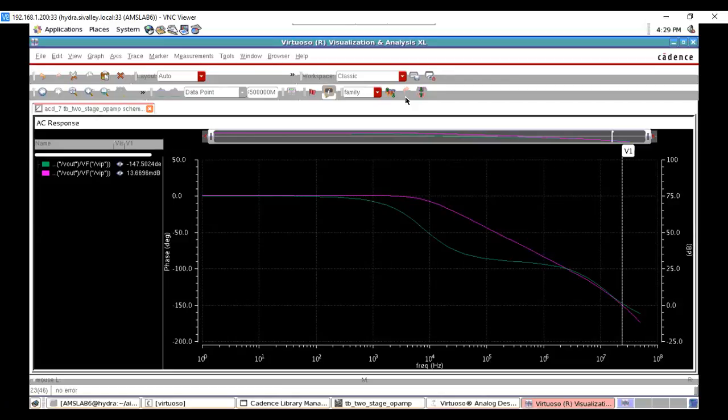Basically I want my Opamp in the time domain to be very fast, operating at high frequency so that my time becomes lesser. High frequency means the unity gain bandwidth should be higher, and at the unity gain bandwidth, your phase margin should be at least 45 to 60°. What I have assumed is 60°, so I have to get 60° phase margin.